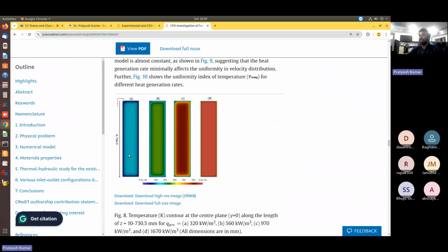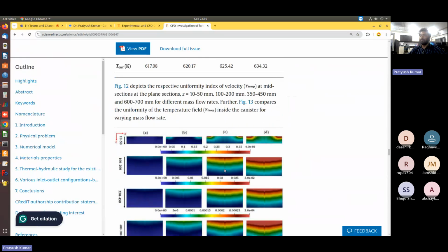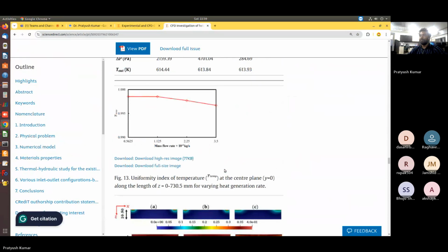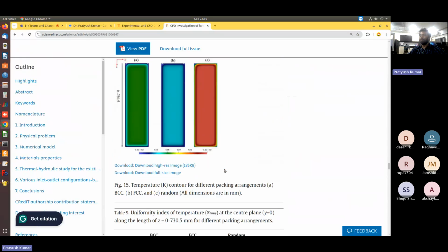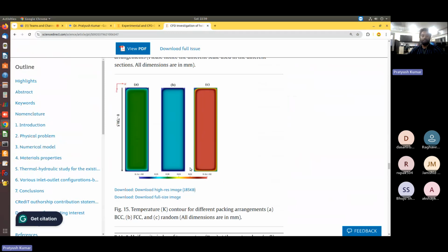Here I plotted the temperature. I just did the state save for this one test case, and then it was done for all the cases. This is also for the temperature. So this way you can optimize your parametric simulation for post processing.